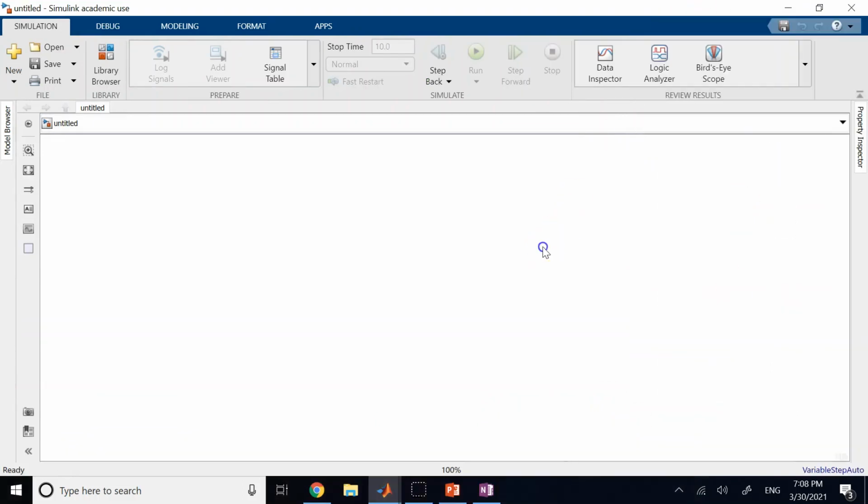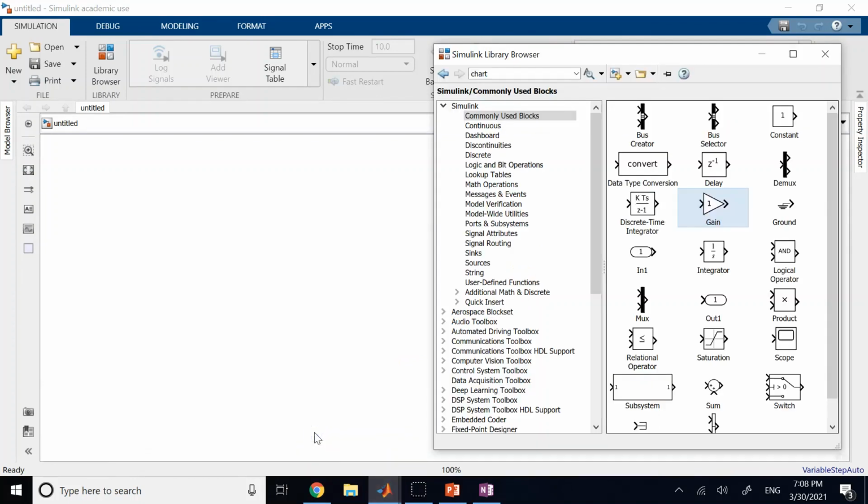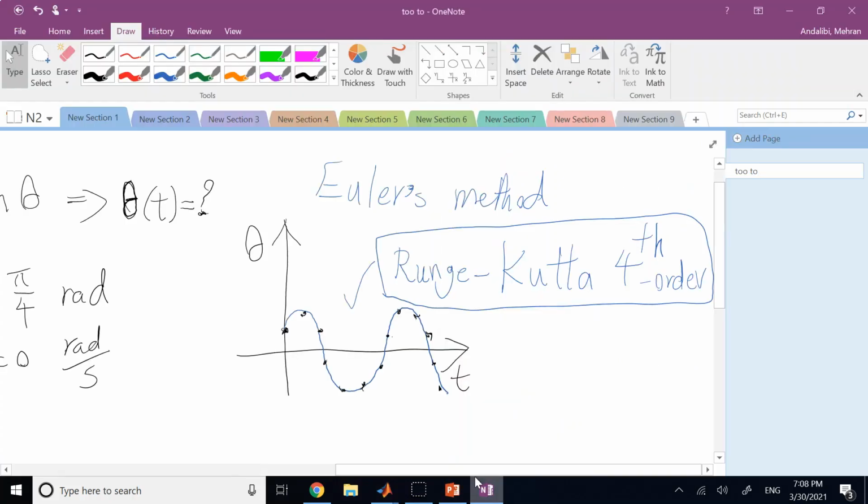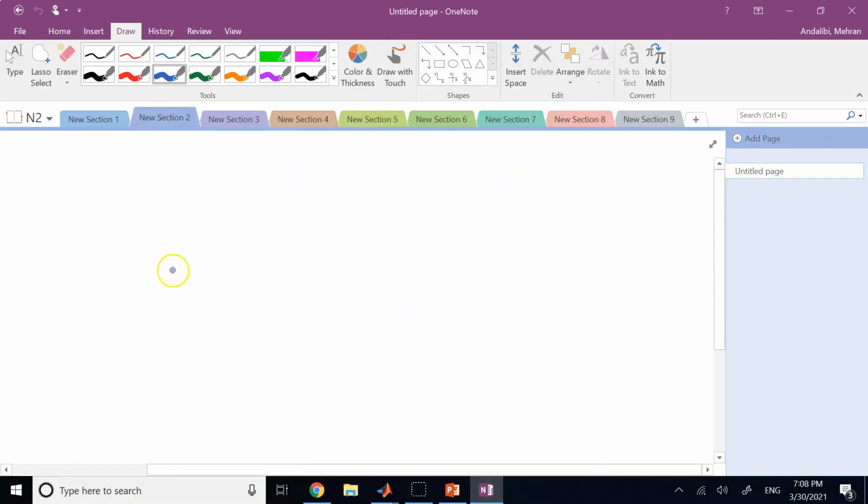Okay, so like what, for example? Well, I want to show you the use of some blocks and for something important. So let's say here I want to look at the projectile problem, right? So the projectile problem, the governing equations for it, if there is no air drag, is x double dot is 0, y double dot is negative g, right?